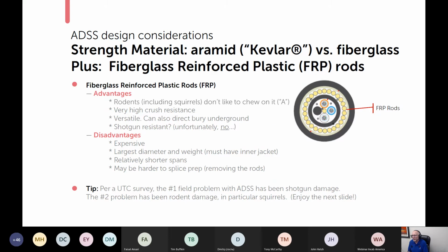So I end up in the realm of spiral vibration dampers are cheap insurance and should always be used regardless of the span length. The short, medium, long, they're easy to install, they're not expensive, and they're a form of, as I say, of cheap insurance.